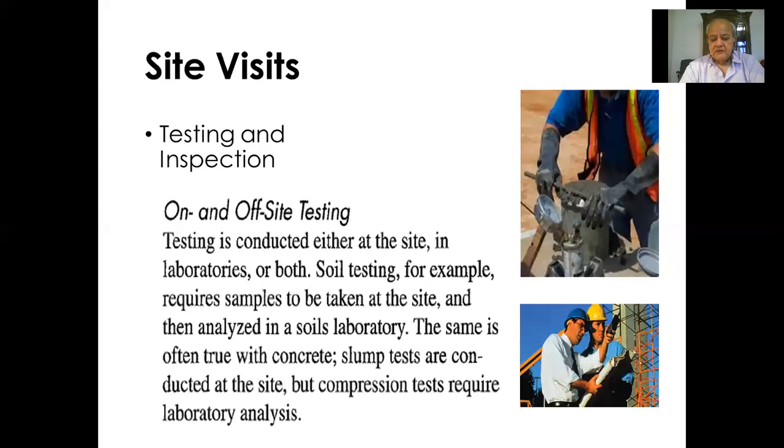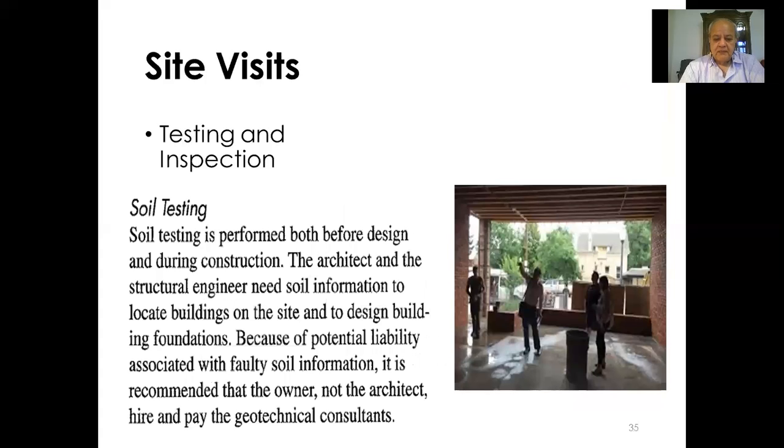But maybe samples of tiles, samples of carpet, samples of paint, they can be done in other laboratories. Of course, soil testing is done before and during construction, so you have to have good soil reports before the construction so that you can design your foundations, and also during the construction if there are any changes in the water table level and so forth.